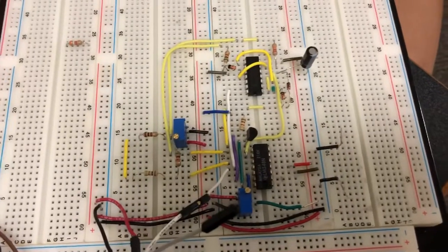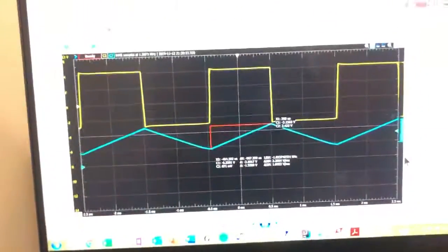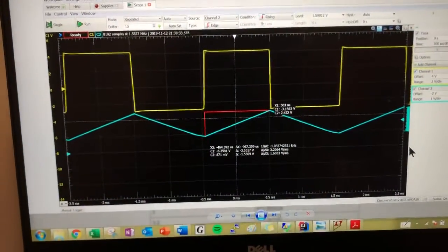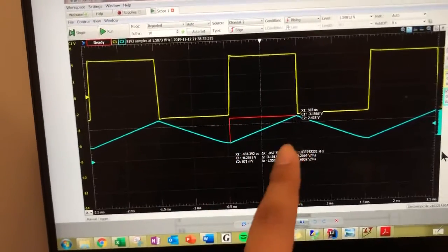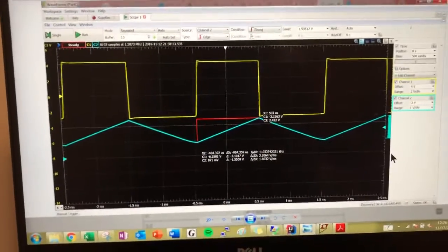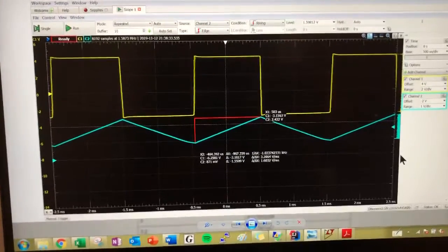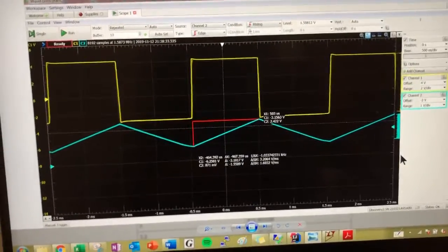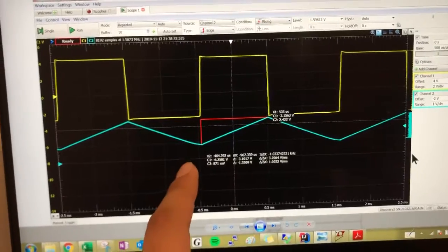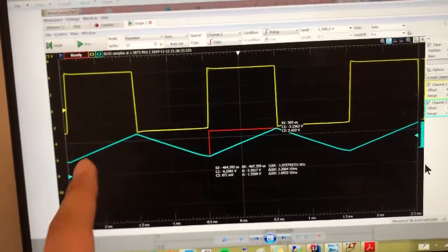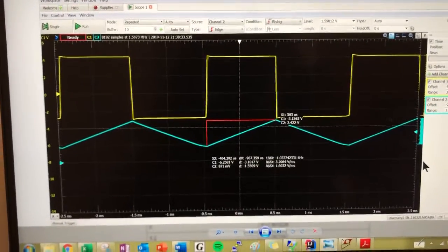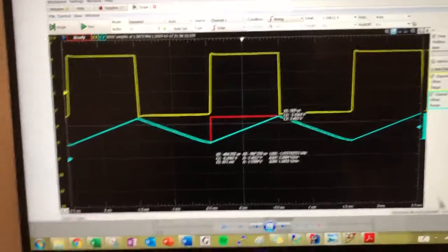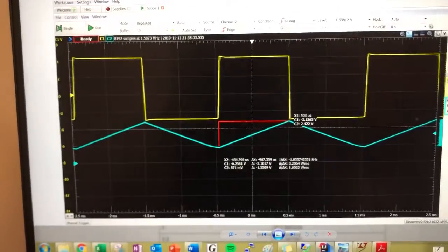And so when we look at the graphs, we can see here VA is plotted and VO is plotted. So VA, which is the voltage at the capacitor, we see charges and discharges at the same rate, which can be explained by the current mirror that we have attached to the VA node A on the circuit. And then here we have our response of our Schmitt trigger. And so we can see that it functions according to the thresholds that we have for it.